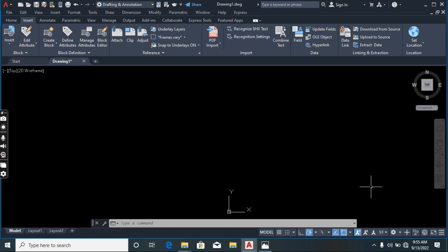You know, most of us that did technical drawing, you know this is an annotation that is showing you that what is represented on paper is what is represented on ground. For our status bar, you see orthogonal mode, polar tracking, and the rest of them. These are what help you to achieve an accurate drawing. When I mean accurate, when you want to do an angle, it helps you to specify it accurately. When you want to position an object on another object, it helps you to specify it accurately.